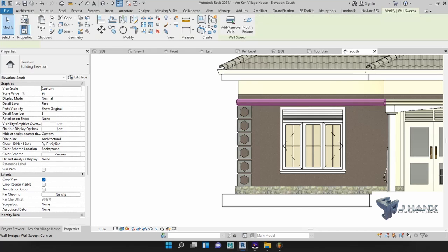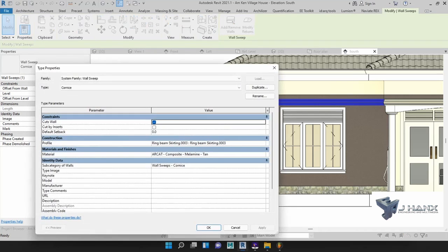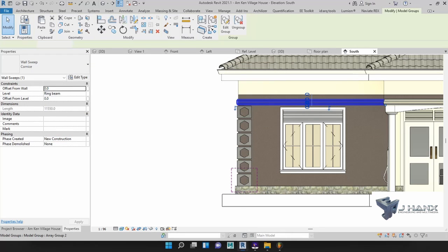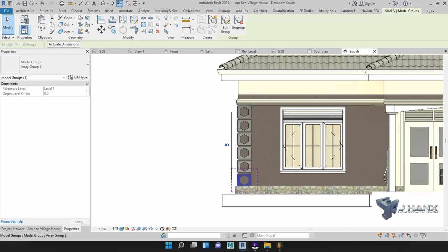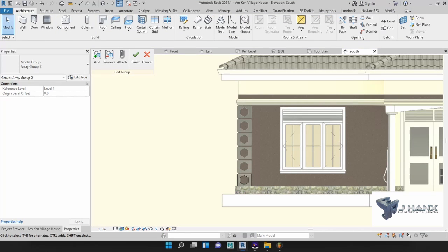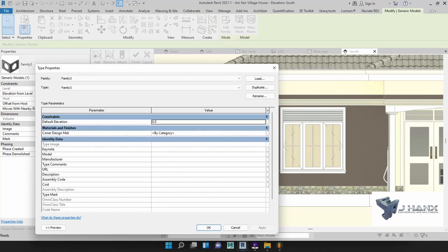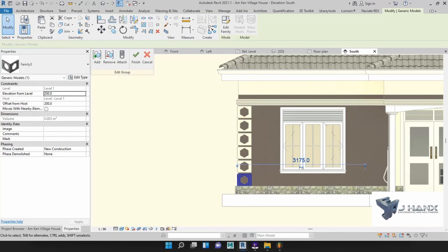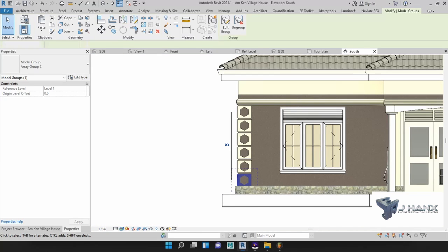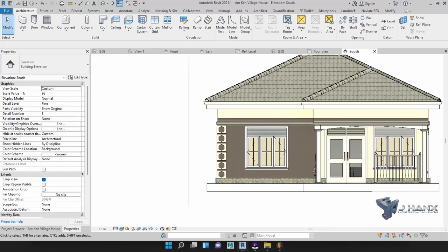When I choose this, edit, I see the material assigned to that is this. I select that material, copy, then go to my corner design. I double click on it, select it, select that group, go inside the type properties. You'll access the corner design material, select it, then copy paste. When you paste, now our material is updated. So like that, we have our corner materials uploaded.